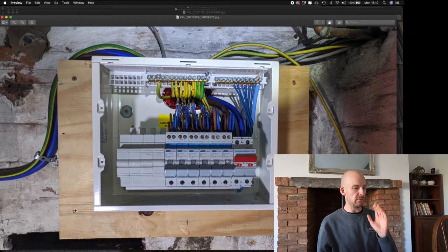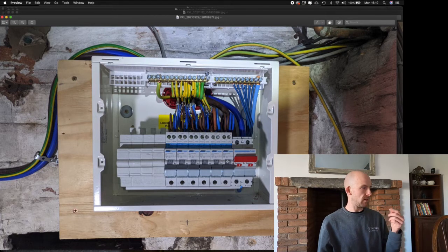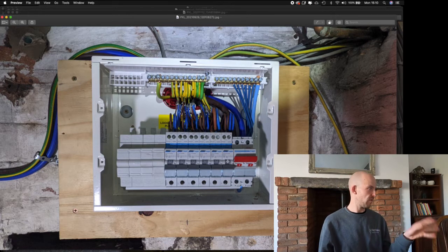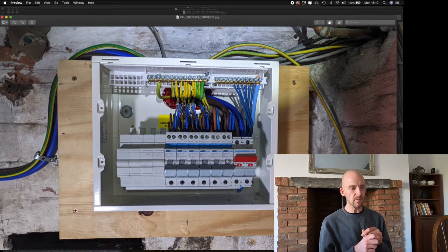So if you've seen some of our other videos, you'll hear us talk about this. They are sensitive to AC faults, so any faults with AC current, like the element in a kettle breaking, something like that. And they're also sensitive to pulsed DC faults. So anything that's got electronics in, computer, fridge, anything that's digitally controlled that has a DC fault, the type A RCDs that are built into these RCBOs will detect that and trip.